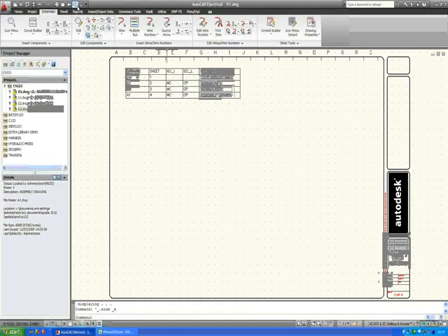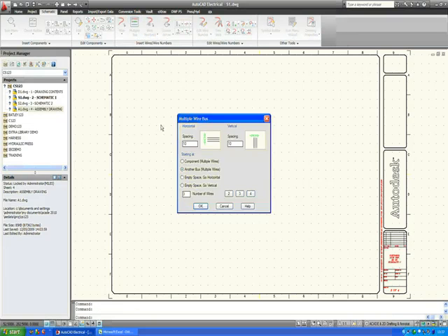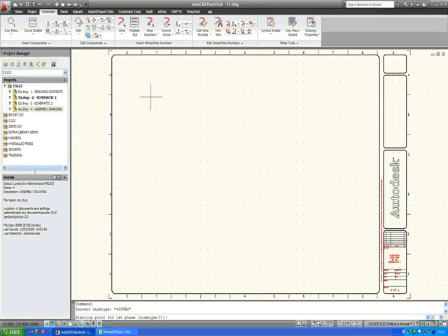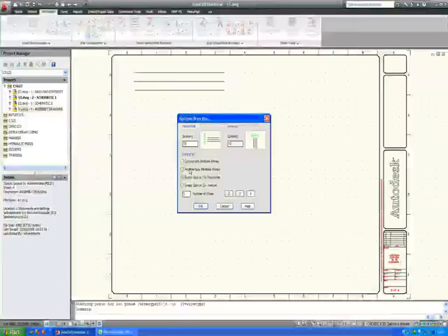I'm just going to go next drawing. So we'll start off drawing three-phase wires. I can select empty space going horizontal. I can specify my wire type and draw three wires in one hit. Right click, that's the key to this software. Right click over a wire, you get wire commands. Right click over a component, you'll get component commands.